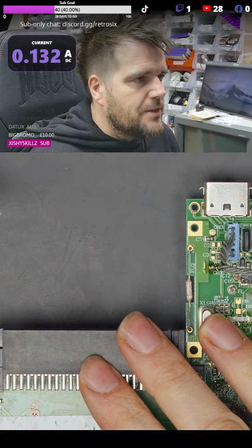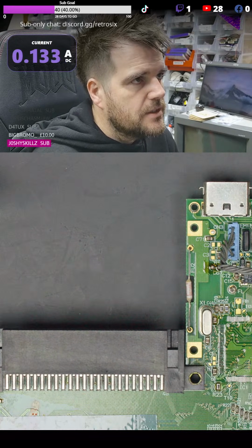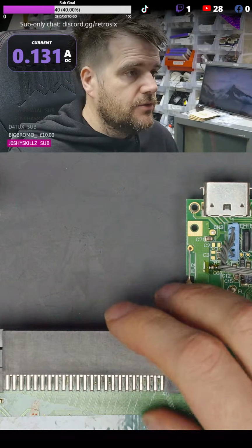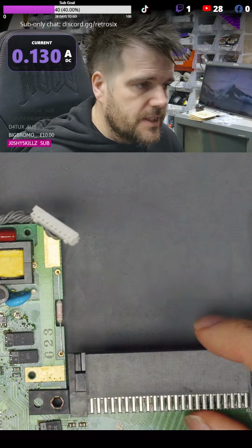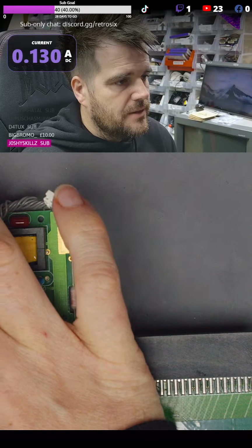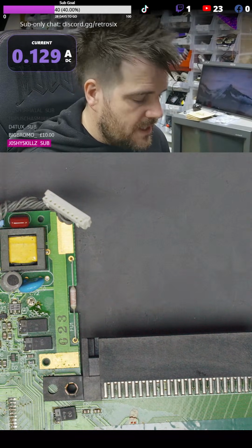So method 1, resistance. Method 2, bench power to see the current. Method 3 is IPA. These are not necessarily in order of cheapness. It would be a multimeter for resistance, then IPA, then your bench power is probably the next most expensive way to test, and we have one other fairly obvious way to test after.